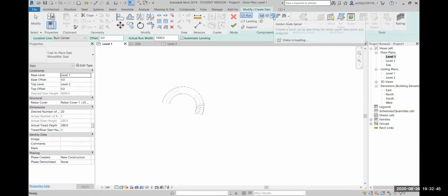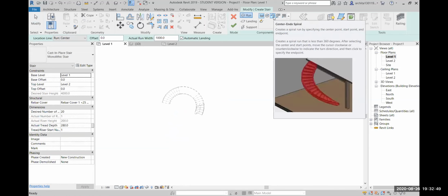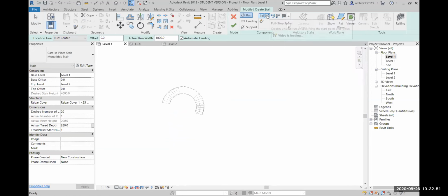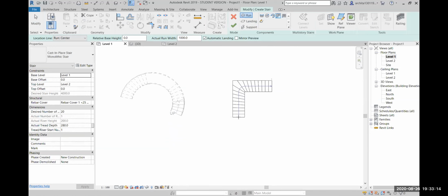Third option gives you the benefit of breaking the staircase into two parts. Second one won't let you break into segments. First is a straight one, but it will let you break into segments. Now, the fourth and fifth options which are there, L-shape winder and U-shape winder. Now, these are going to be presets where nothing can be changed. This is the L-shape. Number of steps are there.